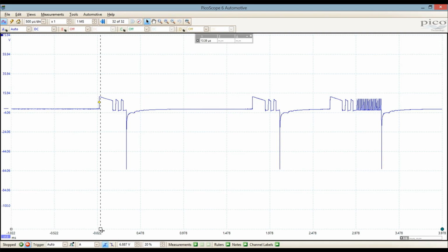After the initial opening, the voltage is pulse width modulated until the injector is closed. This is the same for pilot injection and the main injection. Measuring each of the pilot injection pulses, you can see that they range from 309.9 microseconds to 314.6 microseconds, or 0.307 milliseconds to 0.314 milliseconds.